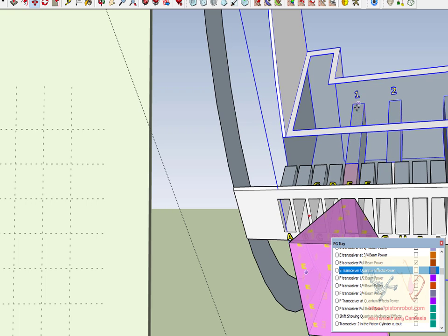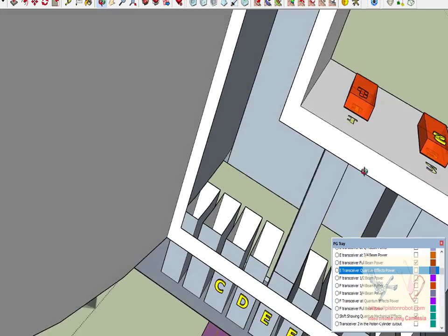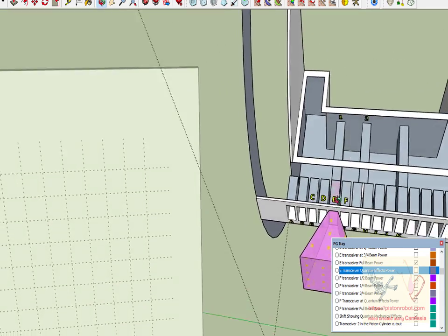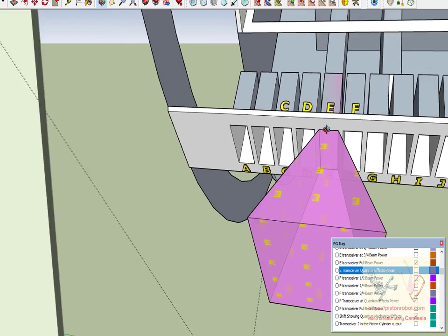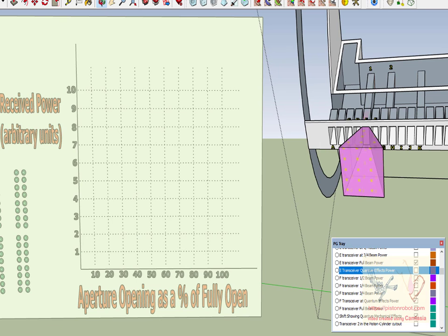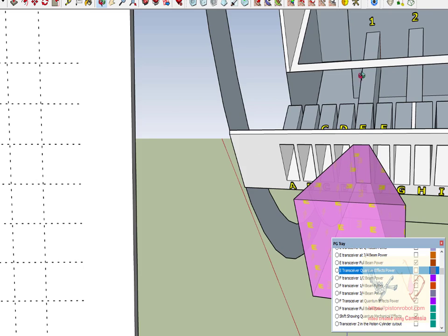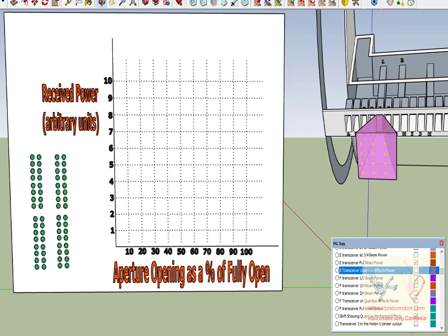here is the channel bringing radio frequency energy from piston transceiver 1 through the wall of the piston, and then out through the wall of the cylinder, and then to the cylinder wall transceiver sitting at position E. And right now we've got it set at a 100% opening. This is all completely lined up, and when we did that and we measured some values,